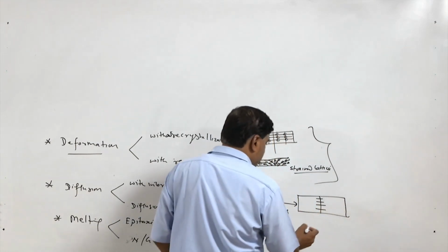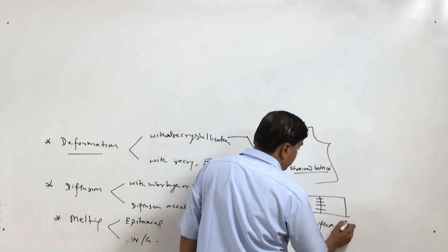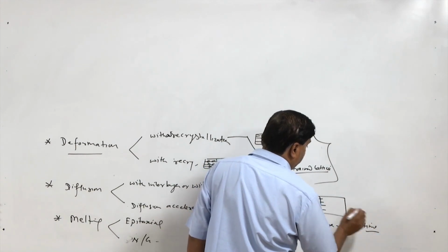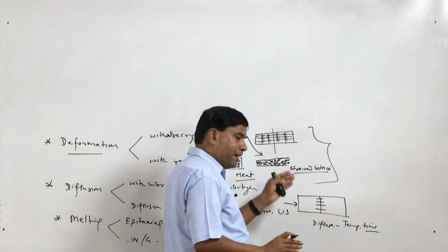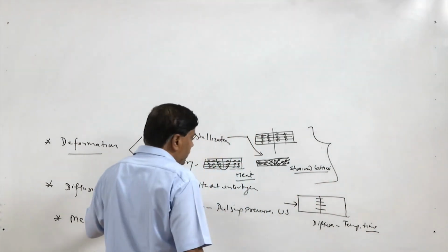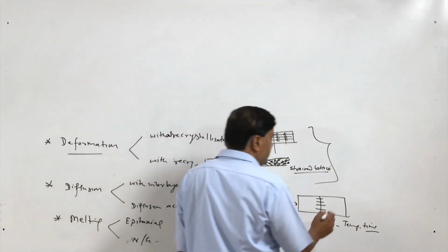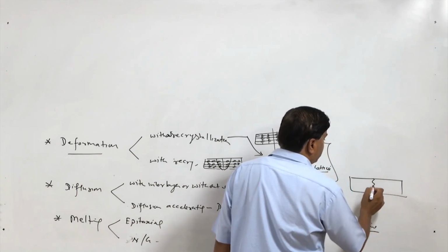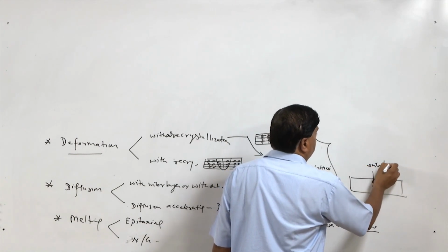So, the diffusion is facilitated basically by the temperature over a sufficient period of time. When sufficient time and temperature are given, the bond at the interface is formed. To facilitate the diffusion across the interface, sometimes to overcome the problems related to surface roughness, interlayers of soft metals are used.